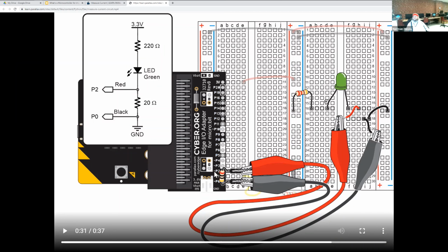Okay. And so it's not identical to a magnetic current-deflects-magnet kind of meter. With a regular multimeter, I would just pull one lead and stick the meter probes in series. Yes, that is true. You are still doing that here, but this is an extra step for our homemade ammeter. Okay. And we're using a small resistor instead of magnetic parts because it's less expensive and it does the job to the extent that we're trying to do it.